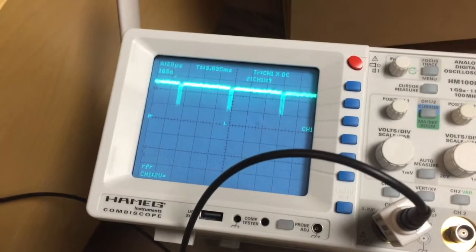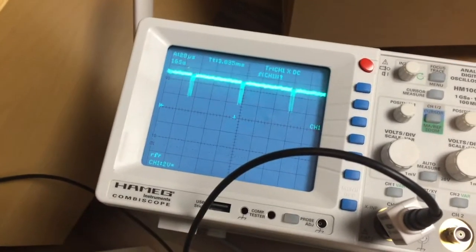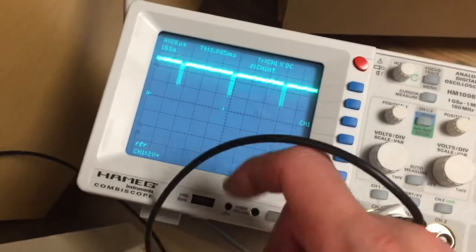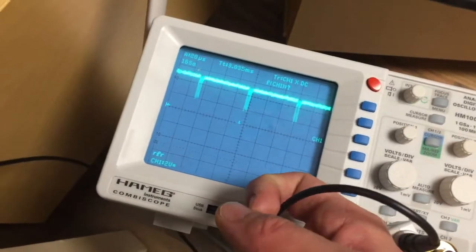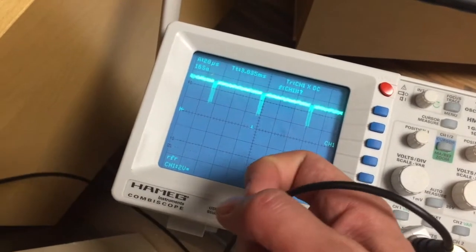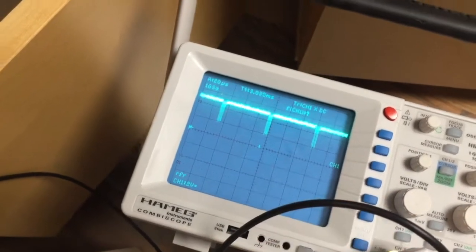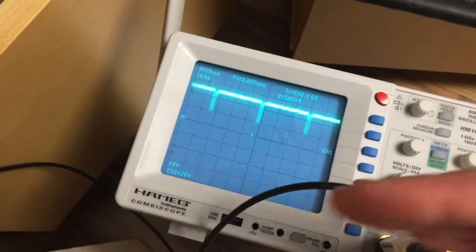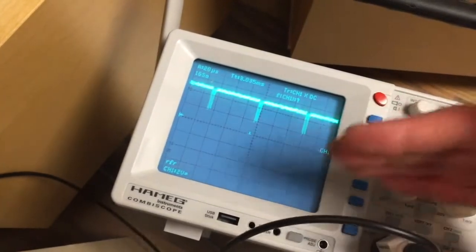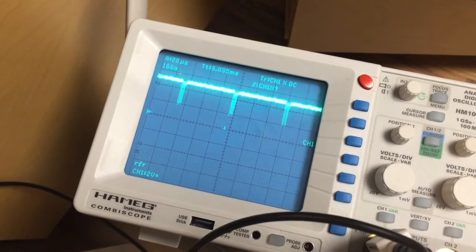But in this case we could also, I think, try to add a resistor to this output signal, which is connected to ground, so that we can pull the output signal more towards the ground level, and then maybe re-establish the difference between logic 1 and logic 0. So let's try if that works.